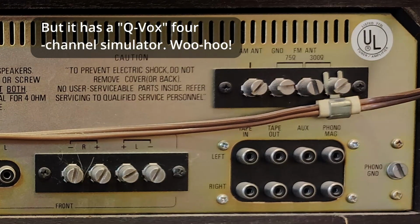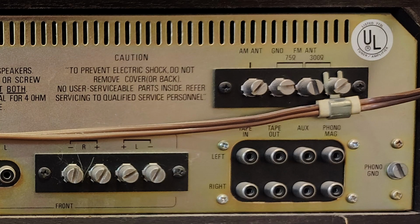And then we have the antenna connection for the FM antenna, the AM antenna. We have a ground connection, which is for connecting to the phonograph. So there's a ground wire that comes from your phonograph. You have your 2 wires that come from the pickup, which go into your phonograph inputs, your left and your right, plus your ground wire comes in. You need to have a good solid ground between those, otherwise you'll pick up noise. The phonograph, as I mentioned, goes through a preamp that's needed for the weak signal coming from the magnetic pickup, and it also has the RIAA equalization.